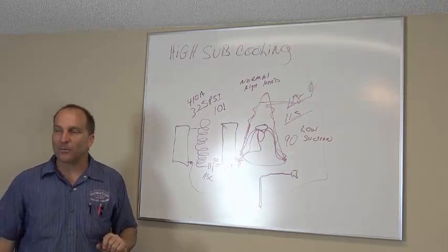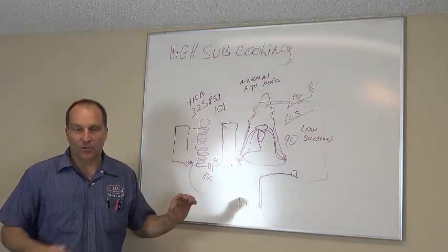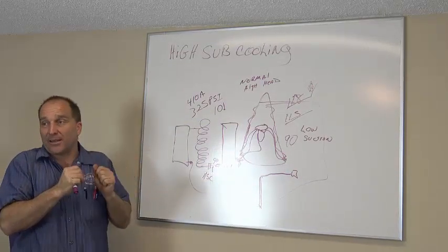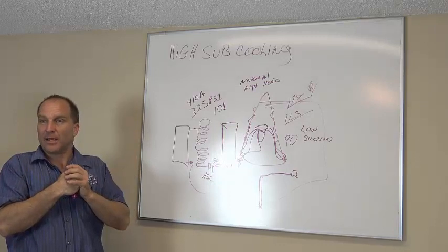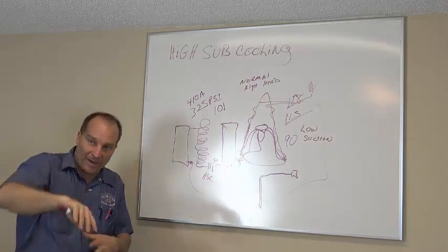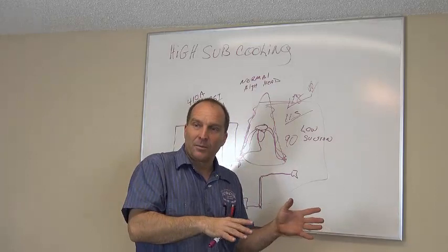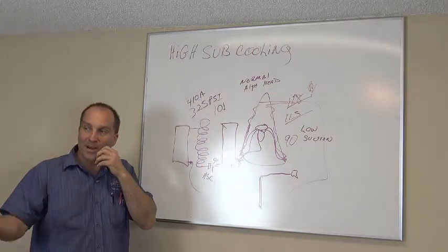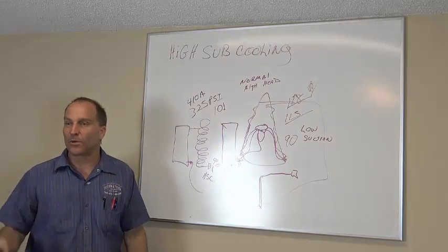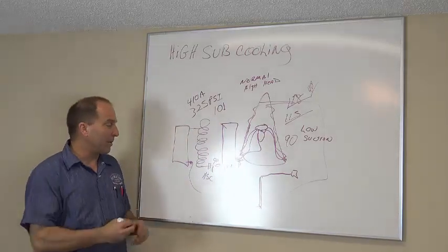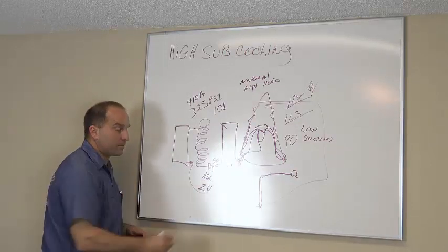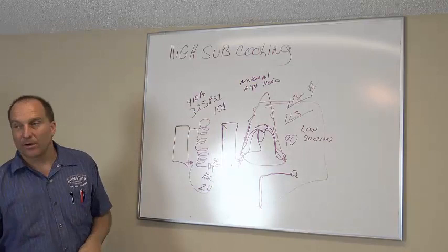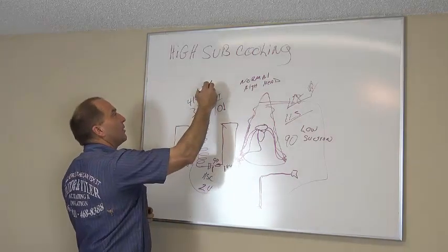And you keep adding more refrigerant in it, so it's like a traffic jam, and it keeps backing up, and it's just staying there now because it can't get out. If you got some of the cars out of the way, it can get through faster, right? But you keep backing it up. Now you're building pressure up in it. Air keeps going over that condenser coil, and it keeps cooling that refrigerant down. So your subcooling went from 11 to 24, okay? Your head pressure went from 325 to 400.